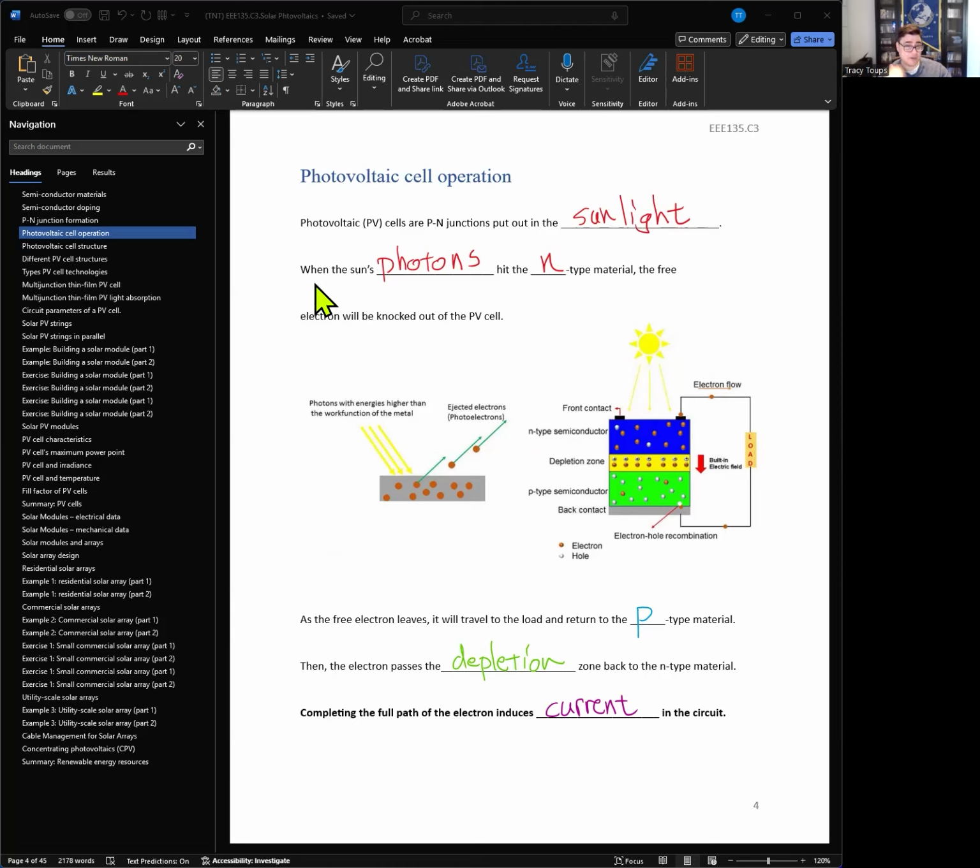The sun rays come to the earth. A sun ray is literally a single photon getting shot like a bullet towards us. Okay, so what ends up happening is you have sunlight falling into the N-type region. Remember, the N-types have extra electrons floating around. Okay, so the sun photons will fly in, kind of like playing pool. If you're lucky, it'll literally strike an electron and shoot it out. It'll pluck it out of the material, and then it'll start moving and find its way outside the material, right? If you give it a path to leave.